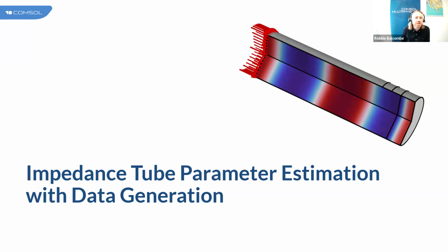And this is something that can be set up in COMSOL as well. We would essentially replicate the experimental setup in a simulation, and using optimization, we would match the results from the simulation with the experimental results. And once they match, we know we found the material properties that we're looking for.